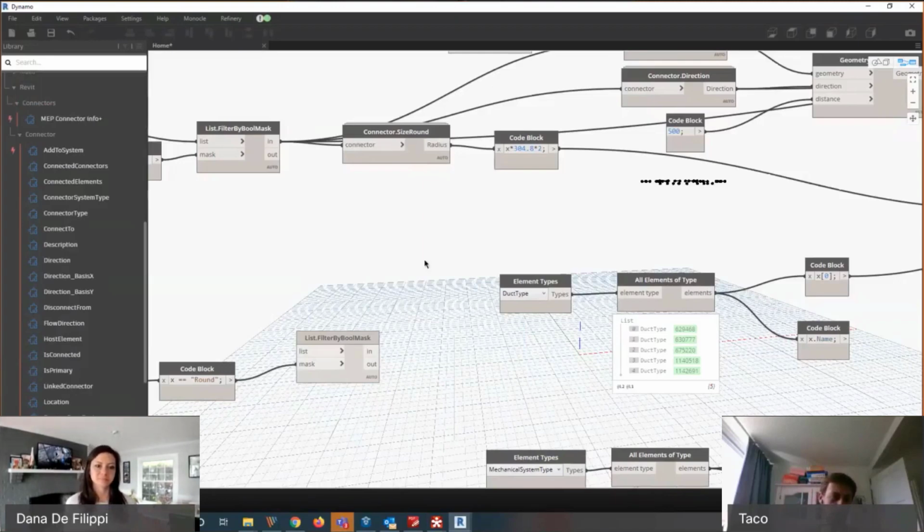And to be honest, sometimes it's just hard to create an entire network the way you set out to do. If you create, for instance, a T on a pipe with the native Revit command from the UI, it will actually split up that pipe. It can just shorten your original pipe, then create a copy and place a T. So one of the two pipes will have a new element ID. And the same thing goes for the T By Two Curves, a node I have. It will create a T on a pipe.